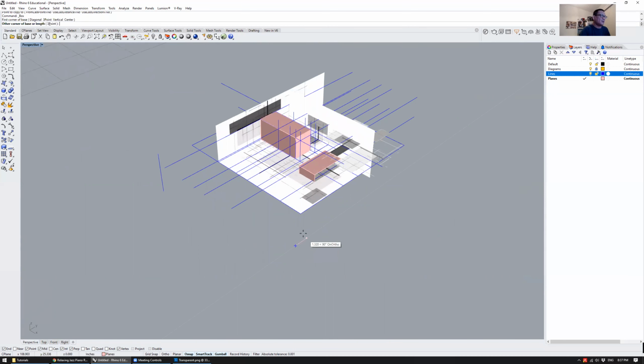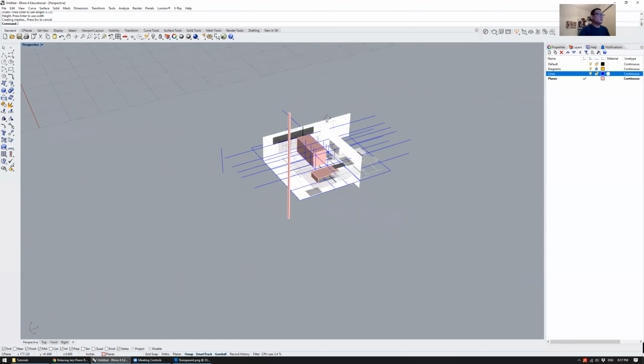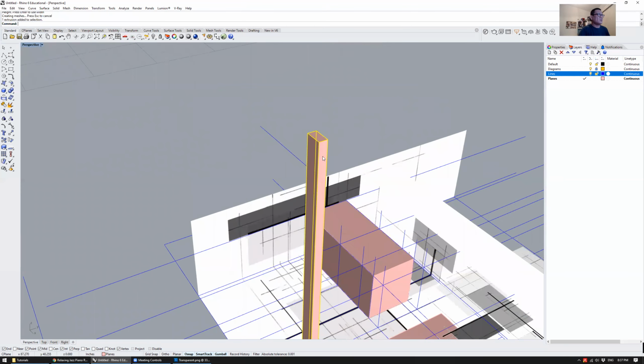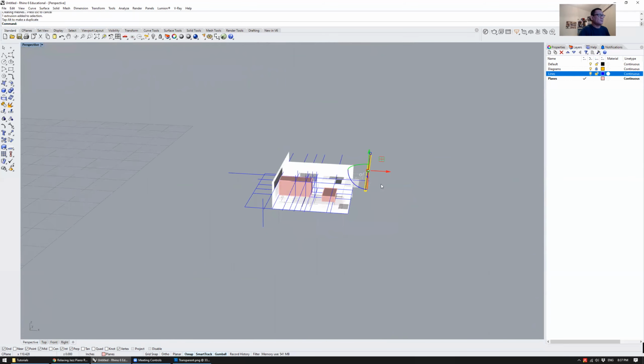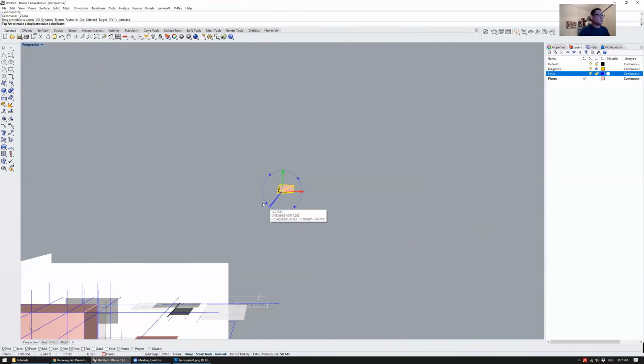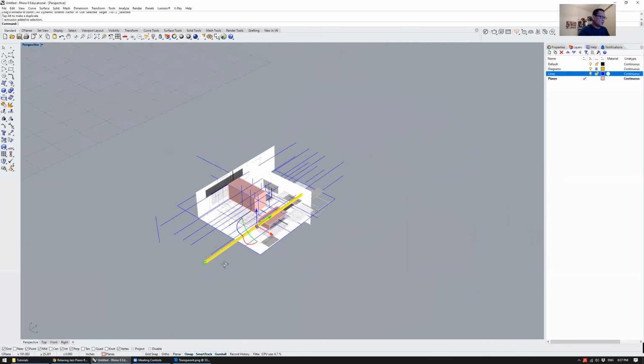So if I'm making a box, let's say this is a linear element. So 1/4 inch linear, 0.25 by 1/8, so 0.125. And let's just make it really long. So this would be an equivalent basswood linear, and just turn it on its side. Maybe turn it 90 degrees in this way, so it's in the tall direction.